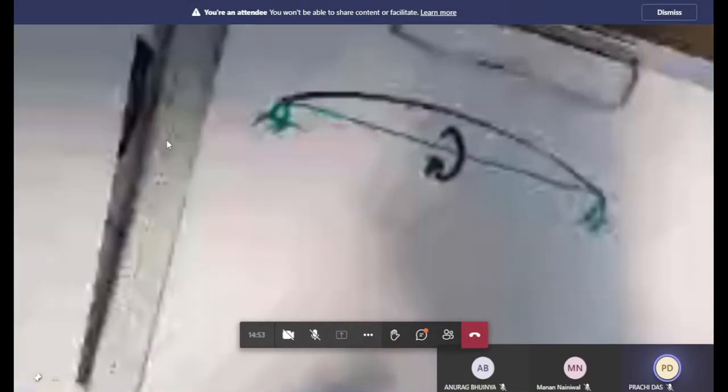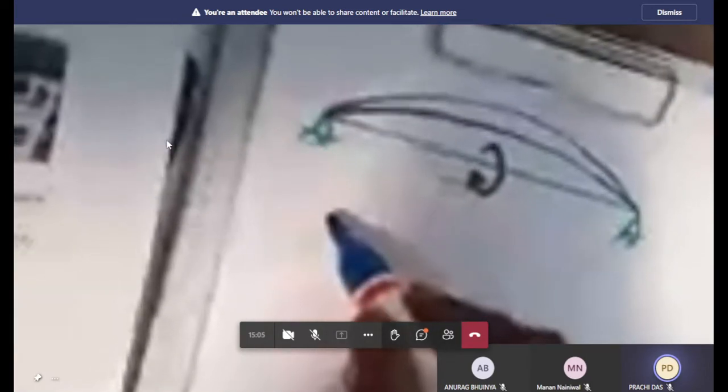Due to eccentricity, the shaft gets deflected, and when we rotate it at high speed, due to the centrifugal force this shaft gets more deflected, which ultimately generates a bow shape. This ultimately changes from one bow to two bows. We can also call it a loop. For the first case there is only one loop, so it will look like this.